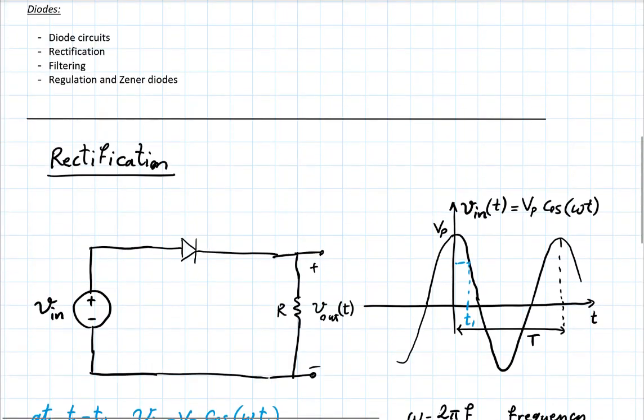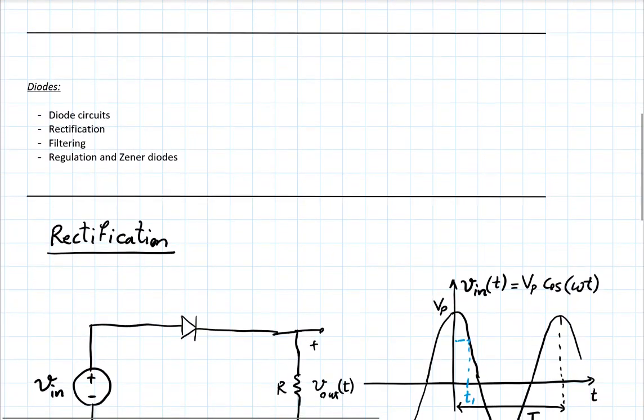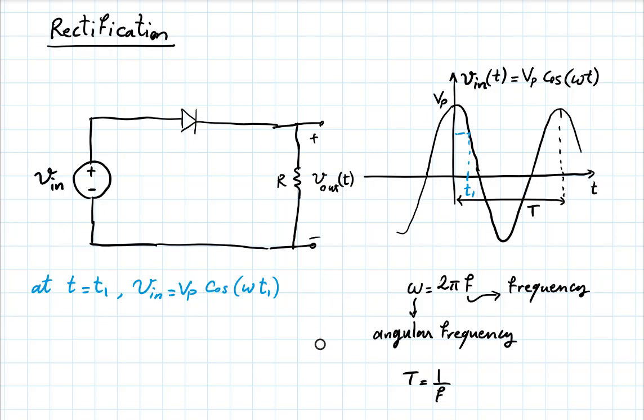As we can see on that graph, that's a positive value. So at that moment in time, V in has a positive value. So imagine it's some 3 volts. Well, if you wanted to solve this circuit for the diode, you have one of two possibilities. And we are, again, looking at it as an ideal diode. So we are not concerned with the whole exponential characteristics, but whether it's on or off. So there are two possibilities.